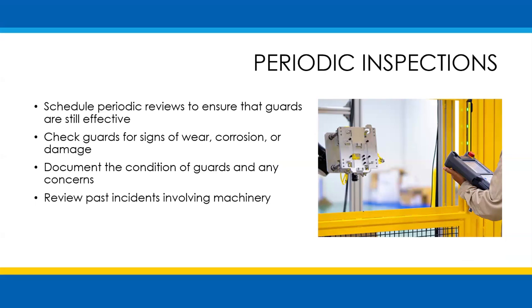Equipment should continually be evaluated and monitored to ensure it remains free from hazards. Schedule periodic reviews to ensure that guards are still effective. Check guards for signs of wear, corrosion, or damage. Document the condition of guards and any concerns. Review past incidents involving machinery.